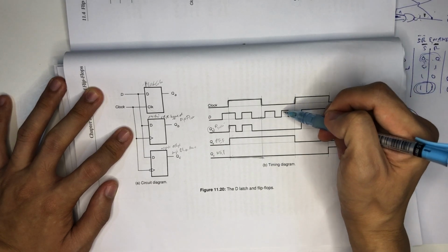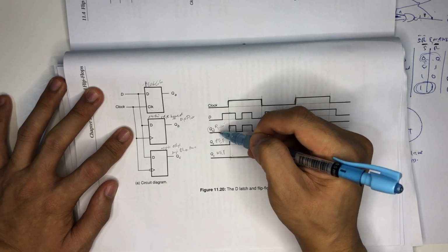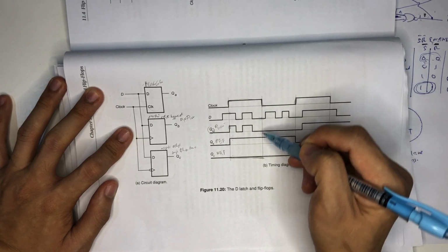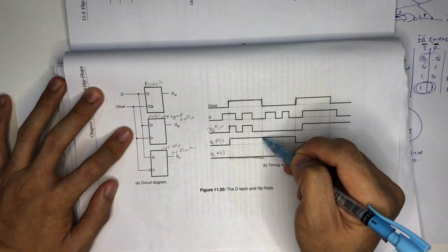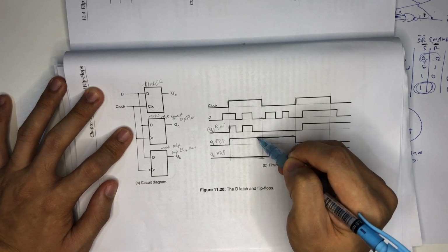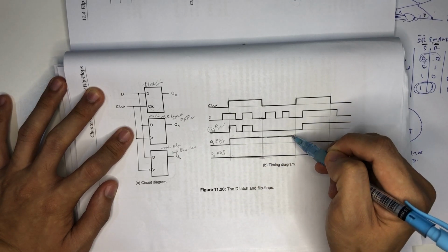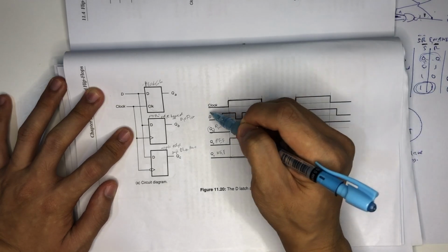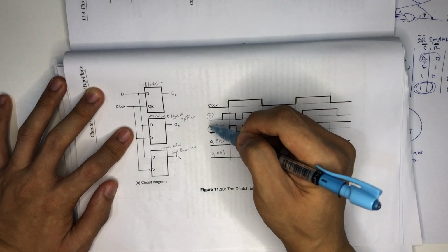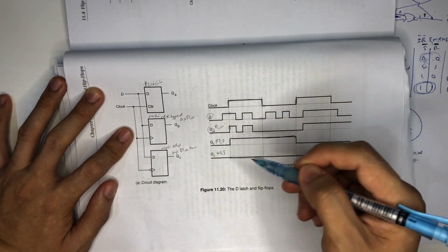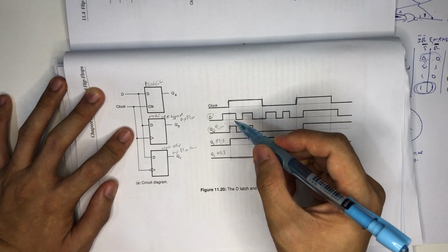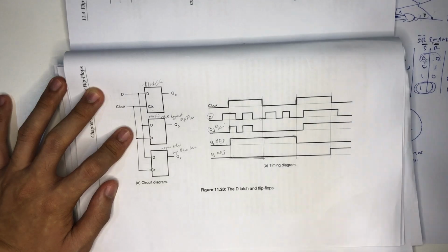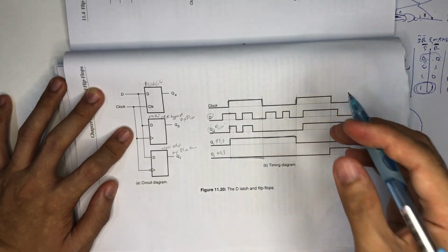And then for the positive edge trigger, if it's the negative edge trigger, it just follows the previous output to be the next output, which is this one. We just follow from this, until we face the next positive edge trigger, then we start changing or considering based on the input of D. Also the same with the negative edge trigger, it only changes with respect to D when there is a negative edge trigger. Otherwise it just follows the previous output as the next output.